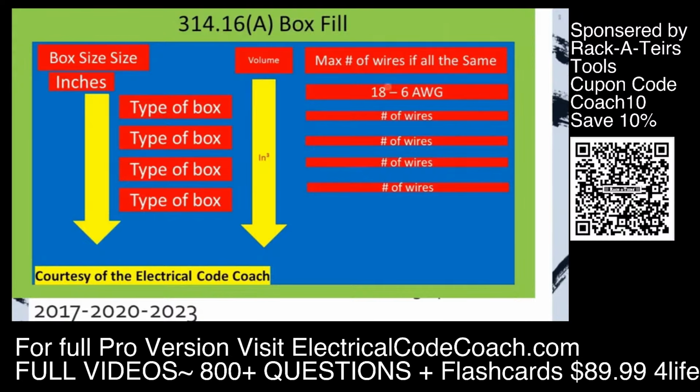Then when we come over here to the far right of the table, it's one of my favorite pieces. It's actually like a cheat sheet. If all of your wires are of the same size, you can use this part of the table and make it very simple on yourself. First thing you'll do is come over and find your gauge of wire. Then you'll come over here and find your type of box, and then come over and tee off with how many wires can fit inside of that box.